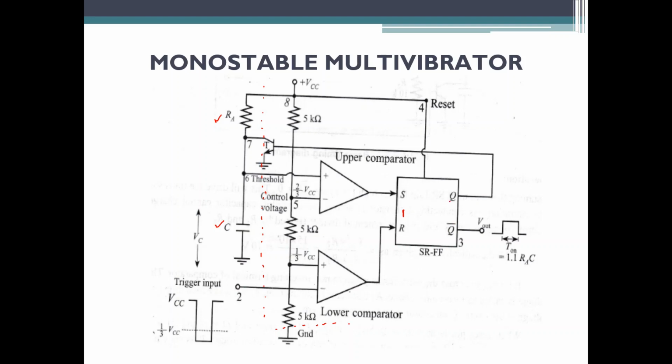See, what is happening here is you are giving an input of 1 to the transistor, that is, base current is given to the transistor and the transistor is turned on. When the transistor is turned on, the voltage given here cannot charge the capacitor. The voltage will flow through this particular path, and your capacitor voltage will remain 0.